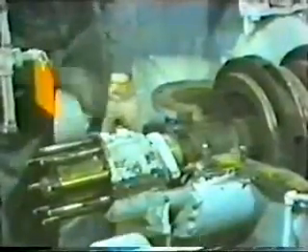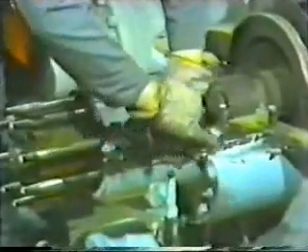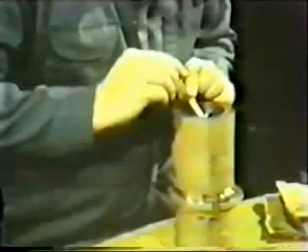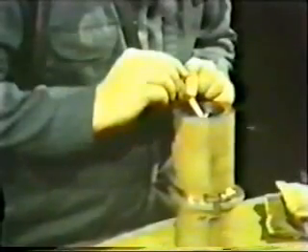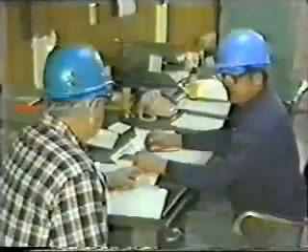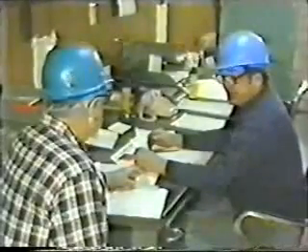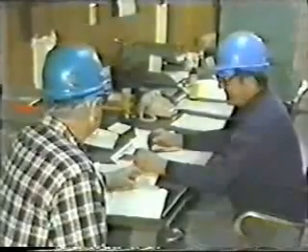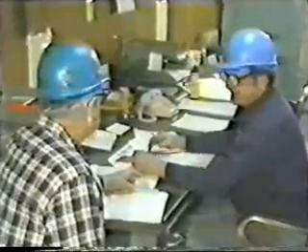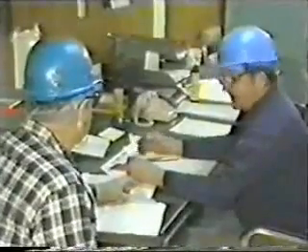The last part of the troubleshooting process is to take steps to prevent the problem from happening again in the future. On certain pumps, some plants may require that you shut down the pump and disassemble, clean, and inspect the bearing. This is because even though there hasn't been any indication of bearing damage, the life of the bearing may have been decreased. If you clean and inspect the bearing, you may be able to prevent future problems that could result from a worn bearing. Whether you have to inspect the bearing or not, think about ways to prevent lubrication problems. For example, you may want to talk with your supervisor about additional procedures or additional training.